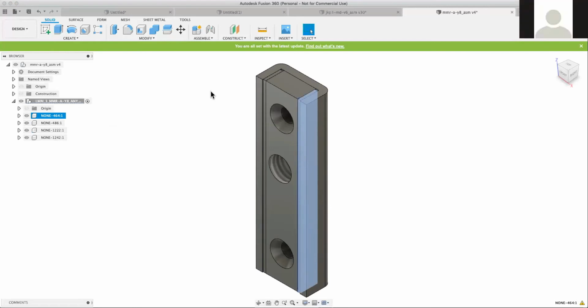Okay. So if you import a file from somewhere else and a parametric variable is named the same as what you are bringing it into, does it notify you that you've got a same name referencing two different variables parametrically? That's an interesting one. When you bring in a step file, there are no parameters that come in. But where you run into that is if you bring a Fusion 360 subassembly into your new assembly.